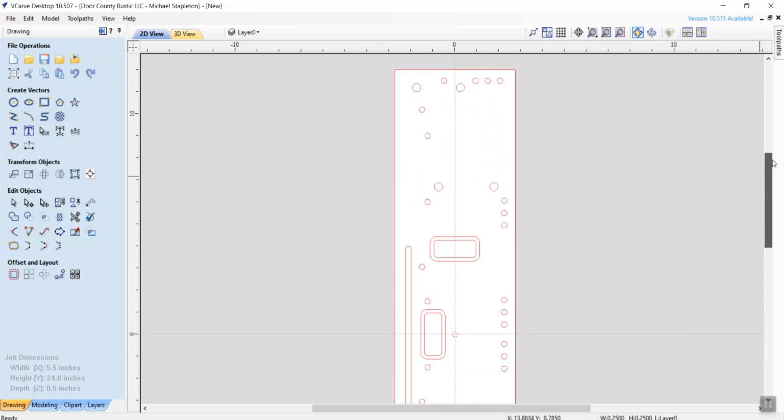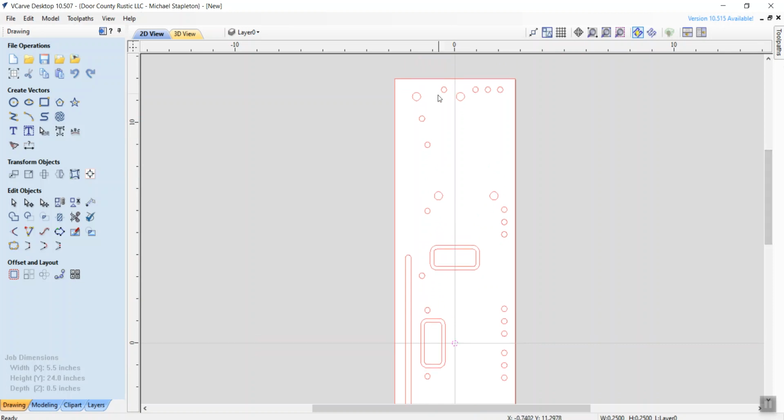So I need to decide where I want to start, basically what kind of group. I'm going to go with these, which are all 3/8 inch holes. So I'm going to click on that, and then I'm going to shift click on that. So now I have those 3/8 inch holes selected. I still have the shift key held down. On those, since they're right in a row, I can drag them. And again, these other ones are still selected, right?